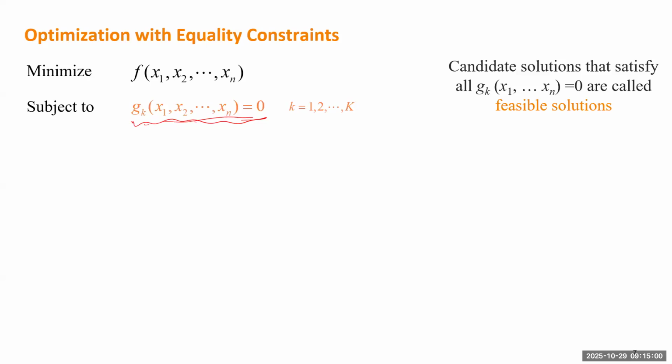If you solve this equation without calculating any function values, the solutions to this equation are called feasible solutions. A feasible solution means that if all the state variables take values that meet this equation, those state variables will present a reliable condition. For a power system, such an equation can be the power flow equations, for example. If all the voltages, currents, angles, and powers satisfy this equation, the system is operating under a normal condition.